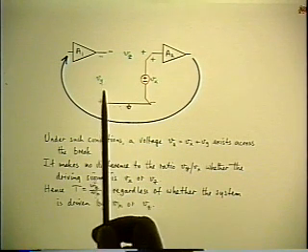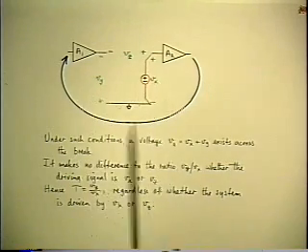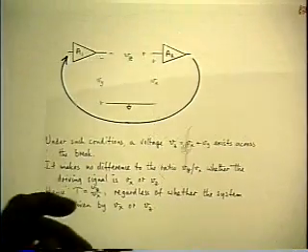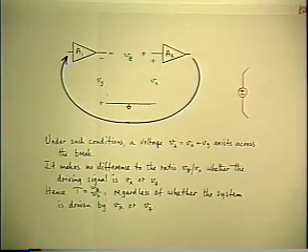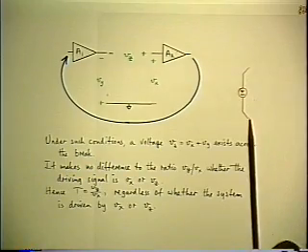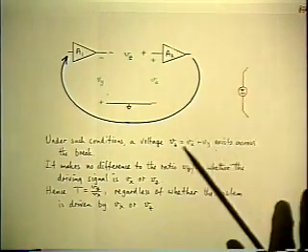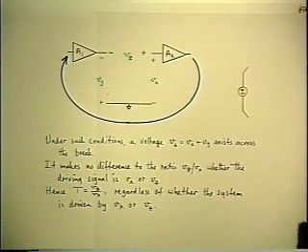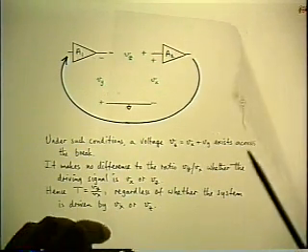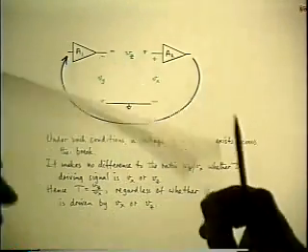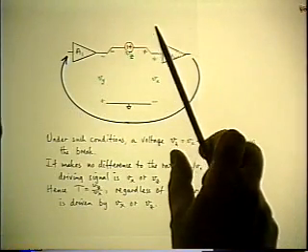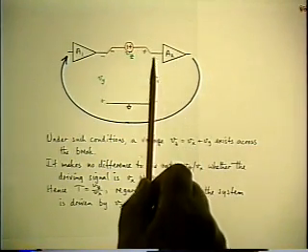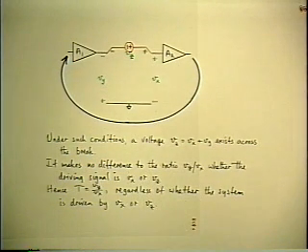Now remember, the answer that we looked for is Vy over Vx, which is 10. Now I'm going to do something different. I'm going to take my signal generator away and put the voltmeter across it and crank up the knob on the signal generator until it reads 11 millivolts. Then I'm going to take the signal generator, which is ideally floating and all that, and connect it across the gap, still set to 11 millivolts. And I take the voltmeter and hang it across Vx. What does it read?